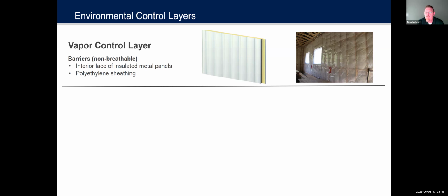And then, of course, you have to deal with your electrical people who are going to come into this building, your plumbing people, your drywall people, and how do you know that someone didn't accidentally rip a hole in this section somewhere? A hole in that system ruins it because it is a barrier. It needs to be complete. An insulated panel being a solid material, you're not going to just rip it open. So it's a more effective barrier because it's visible. You can see that it's a barrier system.